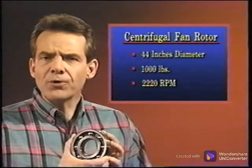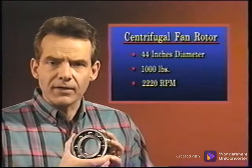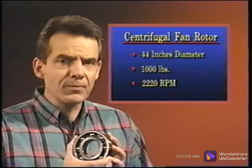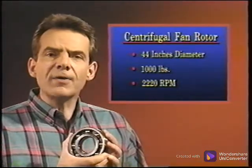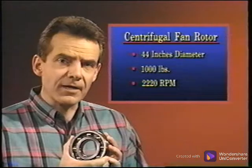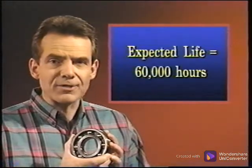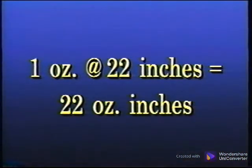Example, a rotor with a 44-inch diameter fan weighs 1,000 pounds and turns at 2,220 RPM. The rated bearing capacity is 20,000 pounds. The calculated bearing life is about 60,000 hours. If the fan has 1 ounce of unbalance out on the edge of the fan, it will have 22 ounce-inches